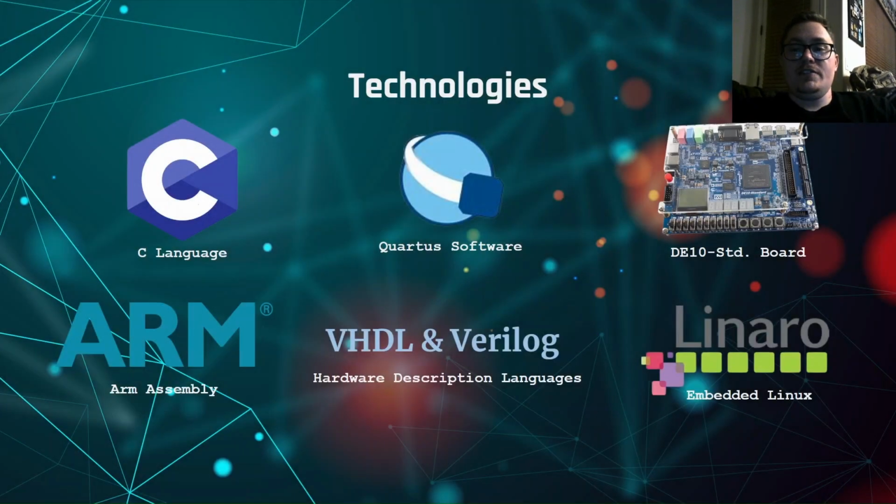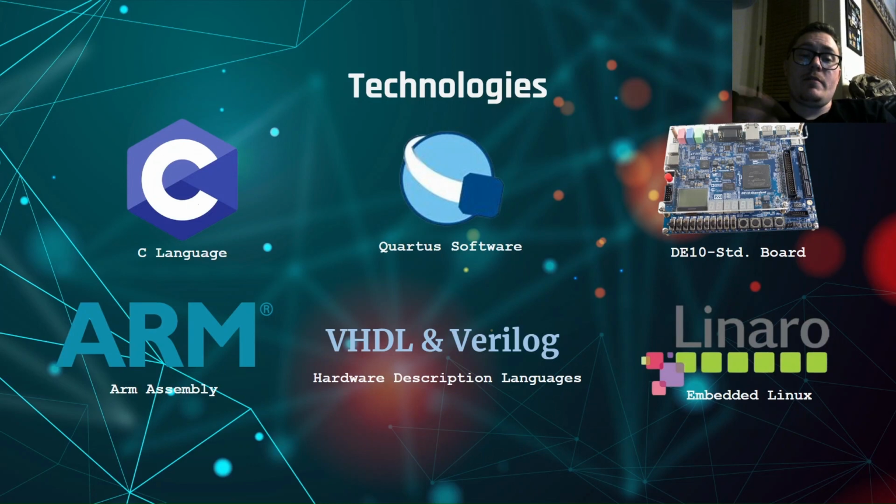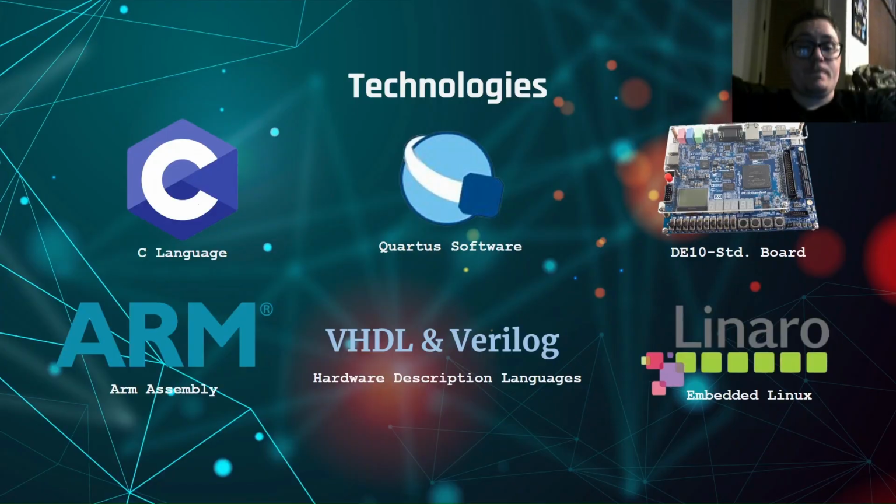Moving on, we have the technologies that were leveraged for this project. The C programming language and ARM assembly language were used for the HPS side of the project, and on the FPGA side I used Quartus to perform functional simulations and waveform simulations, and that's where I coded in VHDL and Verilog. And this is all built on the DE10 Standard board, and on that board we have Linaro Linux, which is on a little chip that connects to that board.